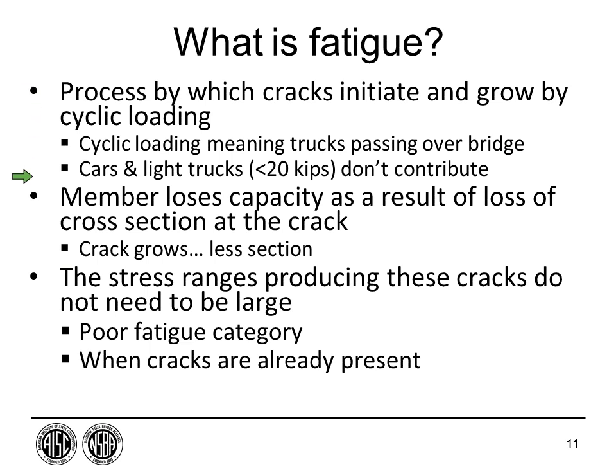Now in some courses people will say, well, the member loses capacity. And they stop there. While that's a true statement, we want to make sure it's clear that the steel doesn't change. It's not losing capacity because it's changing in strength. If you had a grade 50 steel, a 50 KSI yield strength steel at the beginning, and then you put 10 million cycles, you'd still have that steel, but it's like you're slowly saw cutting the steel, and that's because of the crack growth. So you lose strength because of loss of section.